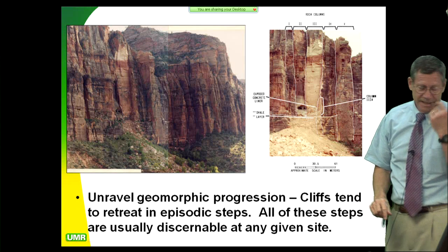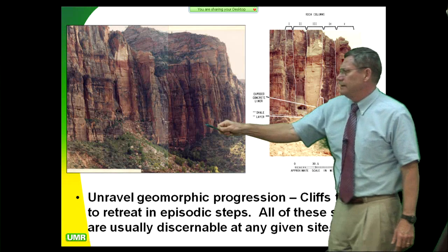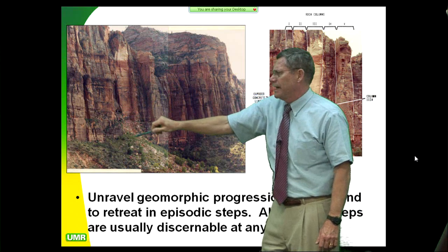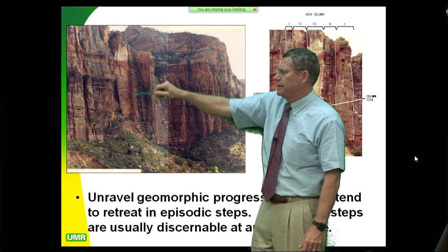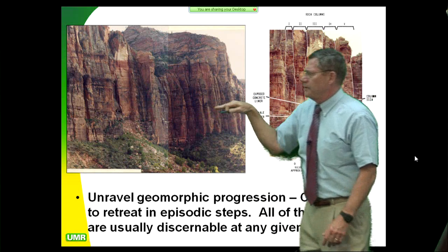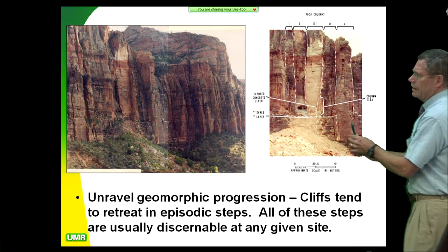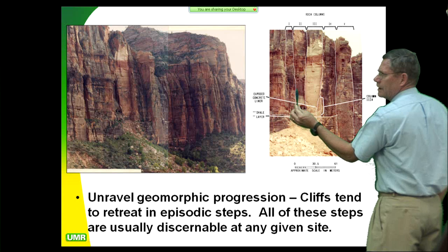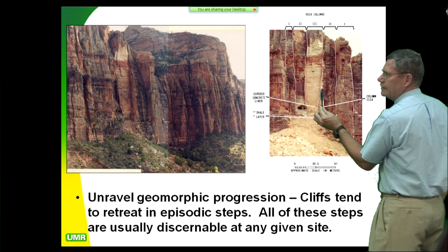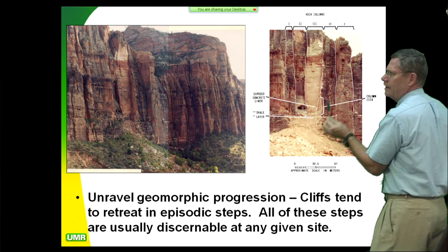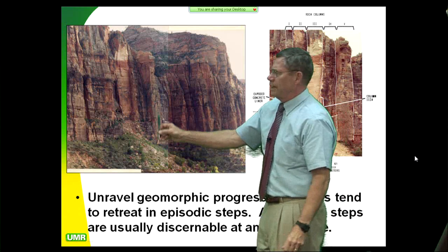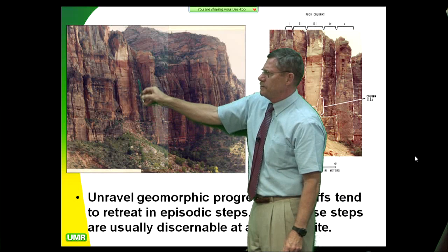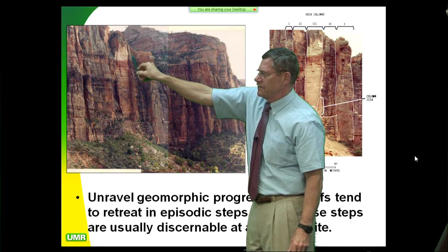Well, what I did is, if we look at an oblique angle, here's where the failure occurred. That's the scar, what it looked like about 21 years after it occurred. And now I'm going to do a head-on view of it. Using terrestrial photogrammetry, I'm going to call this column 1, column 2, column 3, 4, and 5. Now column 5 is this one right here that really sticks out. And column 4 is the one that goes back the furthest. So this one's very curvilinear.